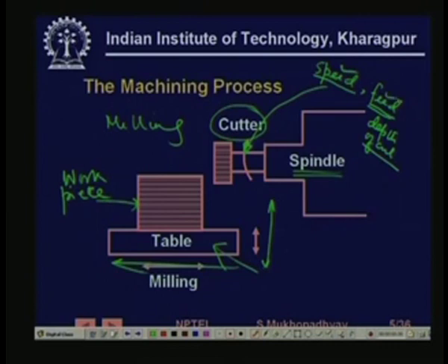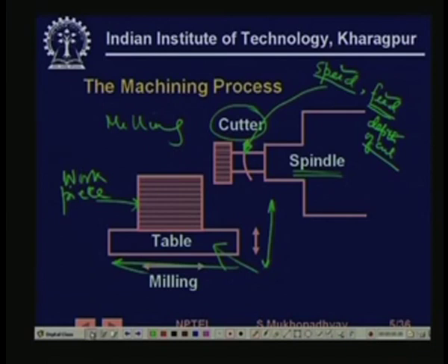So, such parameters are set typically in such machines, and naturally you can understand that even if we want very good surface finish, we generally cannot give very high depth of cut, but for rough cuts, for quick production, we can give high depth of cuts and high feeds. Naturally, you are removing metal like steel, so it puts a lot of load on the drive. So, the idea is to create very precise motions against very high loads.